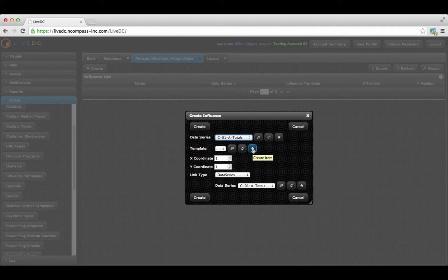For air temperature sensors or humidity sensors in areas where there is no containment, we generally use circles with a 4 to 6 foot radius around the sensor. And generally they have a 25 to 50% overlap with nearby sensors. For air temperature or humidity inside ductwork or for power utilization, we generally use squares that properly fit inside the contained area on the floor plan.